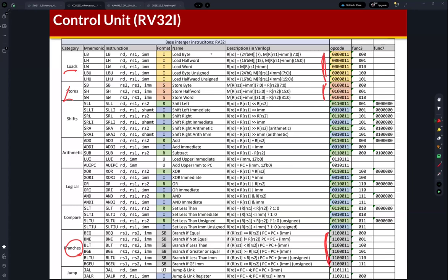And for the R-type instruction, the opcode field is different, but you can find that for the R-type arithmetic or R-type logical instructions, the opcode field is the same. Then the I-type is different, but also you can find that for these arithmetic or logical instructions, we can just use the same opcode field. Okay. So based on this rule, we can define the function of the ALU.